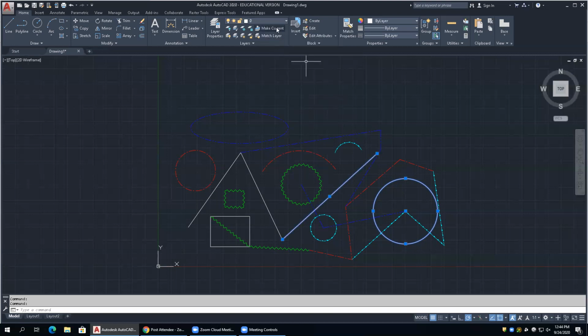If I want to move that to another layer, I just open this up and say, let's take that to layer 3. Once I do that, notice it moved from layer 0 to layer 3. So no object can exist on 2 layers at the same time. We actually moved it from one layer to another. That's what we're doing. So we can move them back and forth.